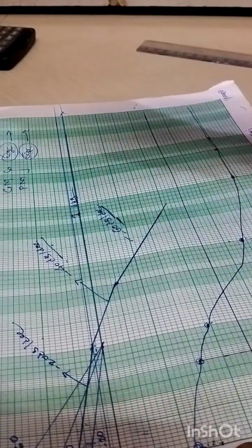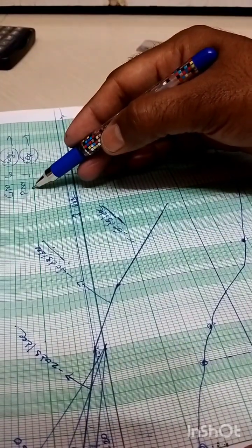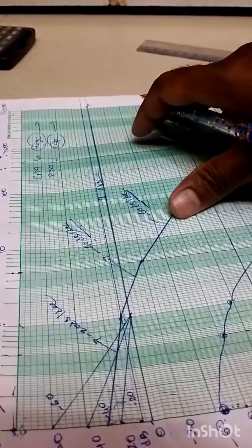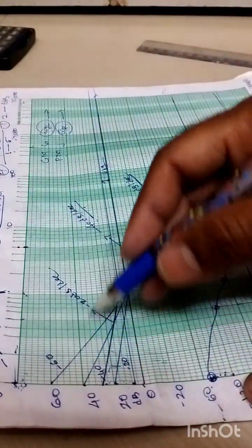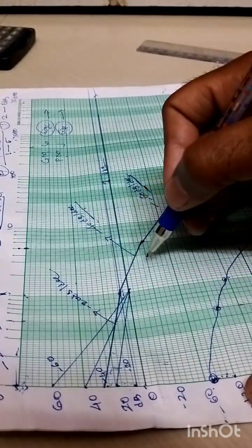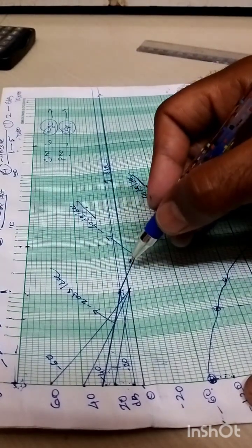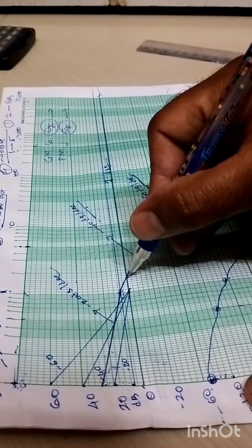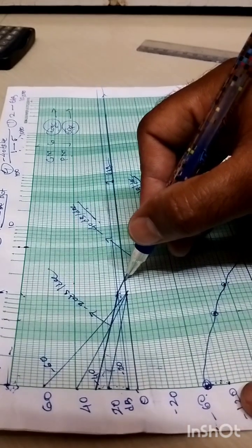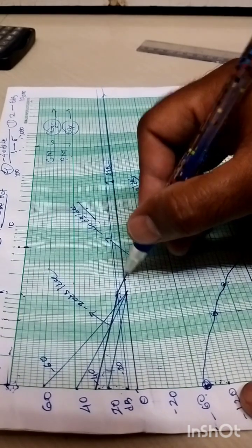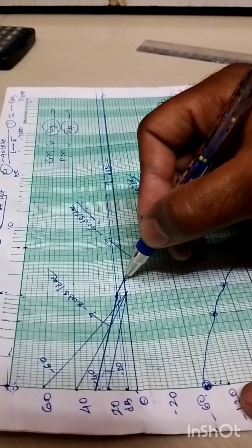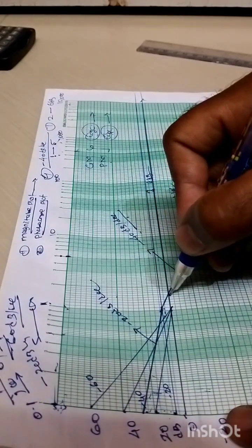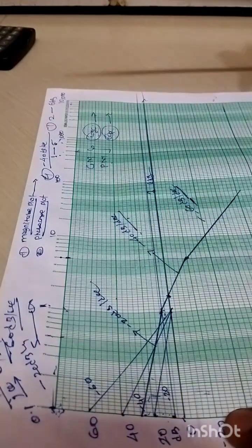So initially this phase margin is to be tabulated from gain crossover frequency, right? Gain crossover frequency means from this magnitude plot we need to observe at what point this magnitude plot intersects this 0 dB axis, means the point at which this magnitude equals to 0, right? So this is the desired frequency, and we need to determine this particular frequency.